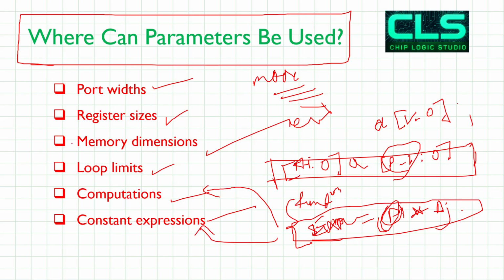So wherever you want to play with the constant values, or you want to change the memory width or anything, wherever you are using constant numbers, you can replace that number with the parameter, and you can change that number anytime with the help of your test bench.